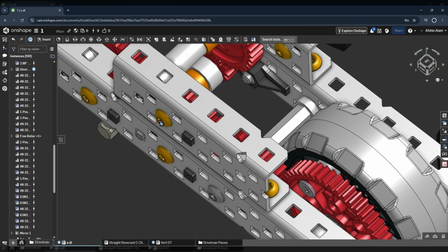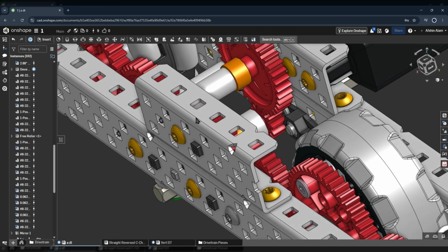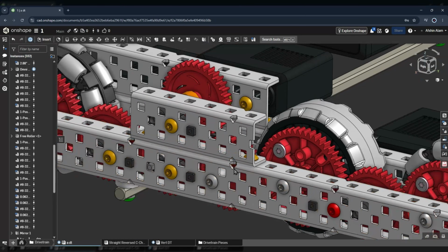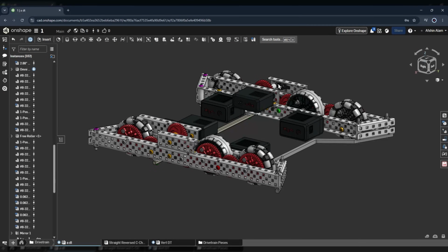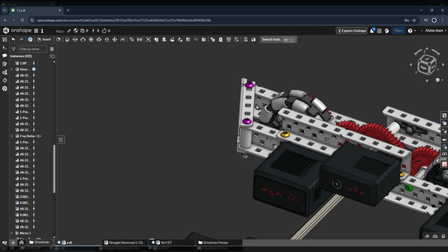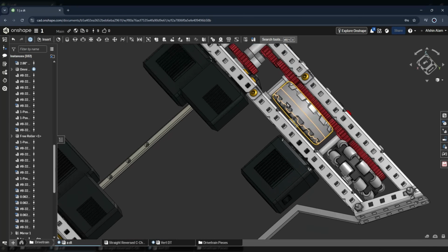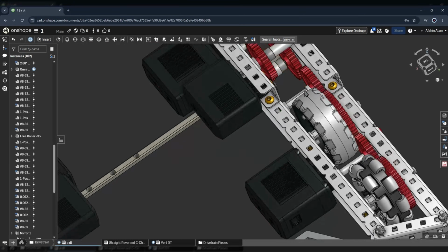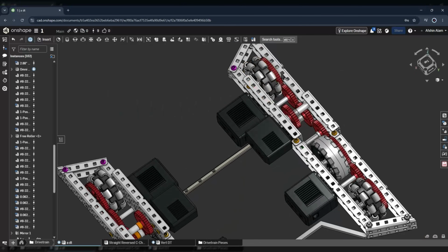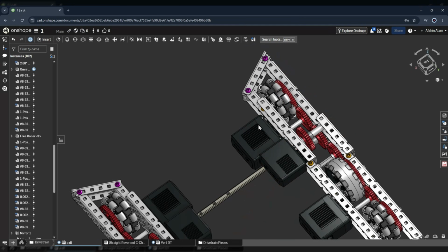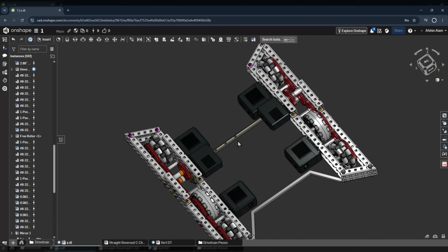And if you're building your CAD, you should know where you're gonna put screws. For example, all of these screws on the drivetrain, if I wasn't making a bill of materials for this bot in particular, I wouldn't CAD all these screws. My first few bots, I never CADed any screws, I never CADed any shafts, unless I needed to cut shafts. So most of the time, you don't have to worry about CADing those. However, it's really important always to CAD your metal, CAD your gears, CAD your motors, CAD your bracings. Those are the really important things that you always want to make sure you have CADed.